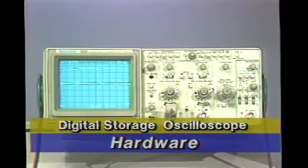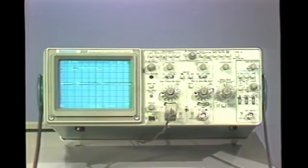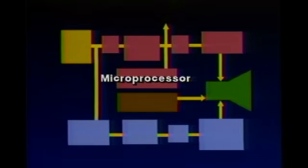A digital storage oscilloscope, or DSO for short, can be broken down into functional blocks. An input amplifier similar to those used in analog scopes, the vertical section, which includes an analog to digital converter that changes the analog signal into numbers, a microprocessor that controls scope functions, a memory for storing the signal numbers, and an output digital to analog converter, which reconverts the signal numbers into analog signals for the vertical output amplifier.